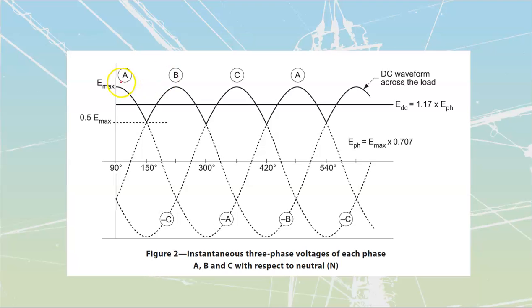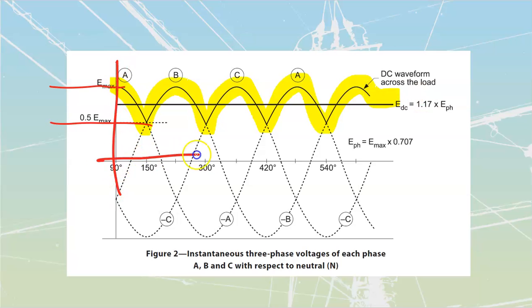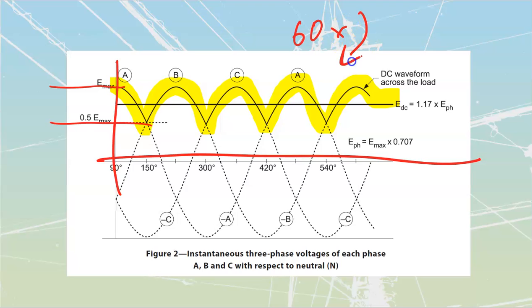The first thing is we are going to have this. Now, I don't know if you remember trying to calculate ripple values of voltage, but ripple voltage is just going to be the amount that might pass through the waveform, which is represented by this line that I see over here. That's what's passing through. We see that it stays always above my 0 over here, so it's a DC waveform. That's going to be called my ripple voltage. And the ripple voltage is not necessarily a great thing for us. Same with that ripple frequency, right? We see that we've got this ripple frequency that is going to be 3 times whatever my source was. If I have 60, then I'm going to do 60 times 3, and I'm going to get 180. That is going to be the frequency of my output ripple on here.